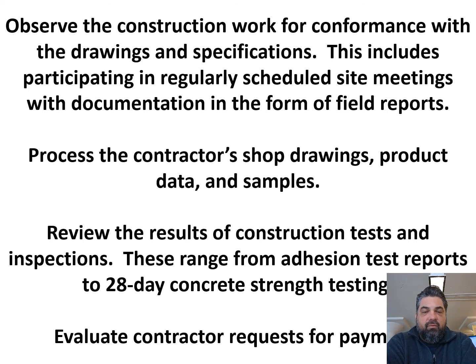You'll be responsible for reviewing the results of the construction tests and inspections. These include things like adhesion test reports for joint sealants and the 28-day concrete strength testing. Now, just because you're responsible for it doesn't mean that you are actually doing all of that. For instance, on the 28-day concrete breaks, you're going to forward those to your structural engineer, who is a subconsultant of yours, right? To review those and advise.